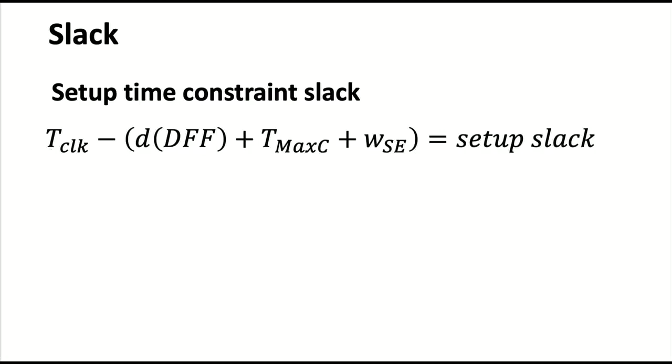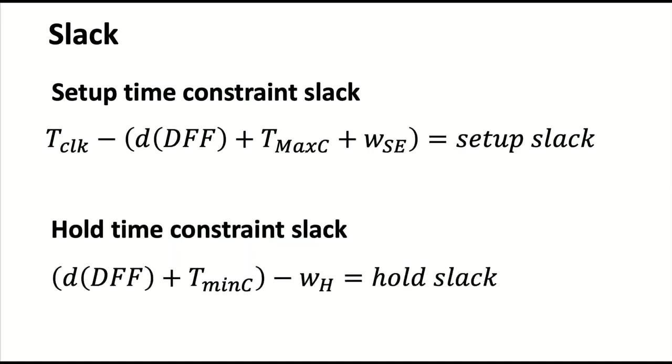Okay, so it'll say worst negative slack, because you don't want any negative slack. You want your slack to be at least zero. At least, right? At least zero. And then it'll tell you the most negative one. But you won't have a negative one, because I have yet to see a design that didn't meet timing. Okay. Again, we do the same thing for the hold slack.